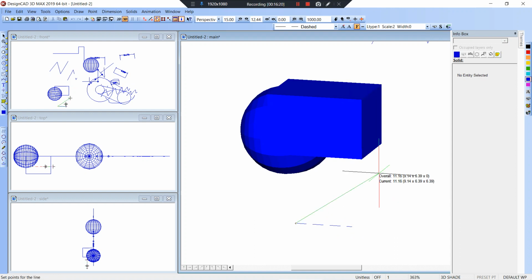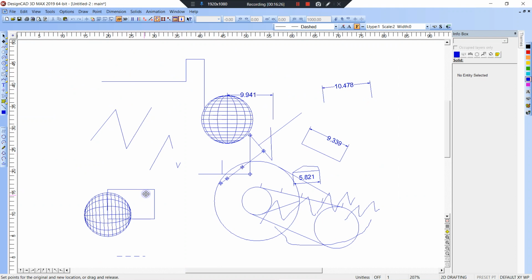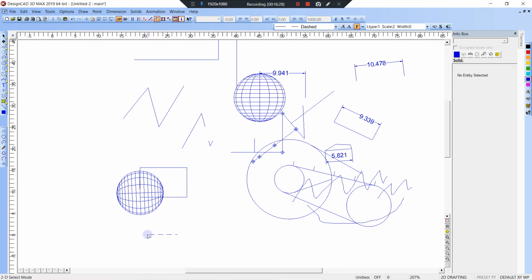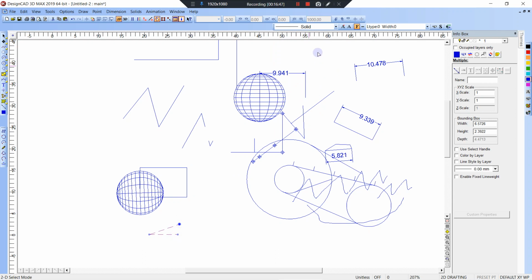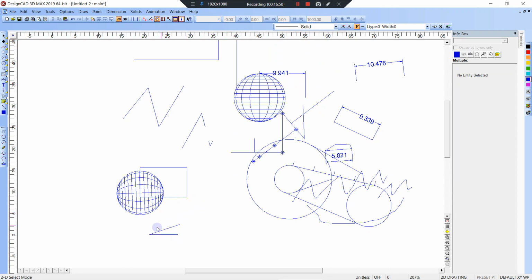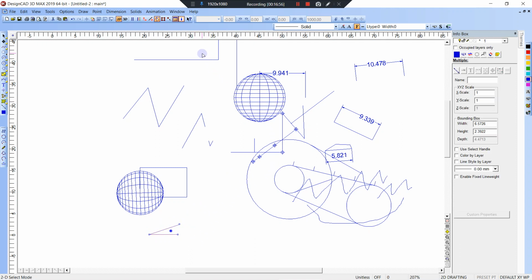You can't do J custom angle, so you actually have to go to 2D, right? And then where's that line right there? V, J, C custom 20 degrees, enter. And then tell it how long we want it, enter. And let's go back to regular line. Now, see this, I can paste it on that cube, Control C. And then I can open up the view to 3D.